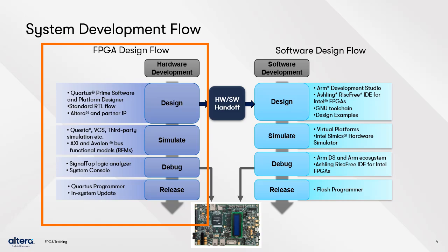Here's the system development flow. Since this is the hardware development flow training, the objective is to learn about the features in the left column. Altera provides tools necessary to carry out software development, covered in separate online training and resources. On the hardware side, we start with the Quartus Prime design software, which is used to synthesize, then place and route RTL source files. The Platform Designer system integration tool generates the RTL sources. It is a front-end tool that allows you to bring together various IPs quickly and automatically generate synthesizable interconnects.